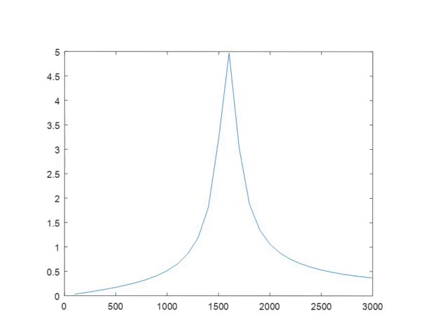Of course, you can define something here called the cutoff frequency. Cutoff frequencies are the frequencies at which the response will drop to 1 over square root 2 of its top value. So here the maximum value is 5, and the way we see why it's 5 is because we have two equal resistances, RS and RL. So RL gets half of the source. The source is sinusoidal with amplitude 10. Then here the output is sinusoidal with amplitude 5. So you have to determine this term, which is 5 over square root 2.